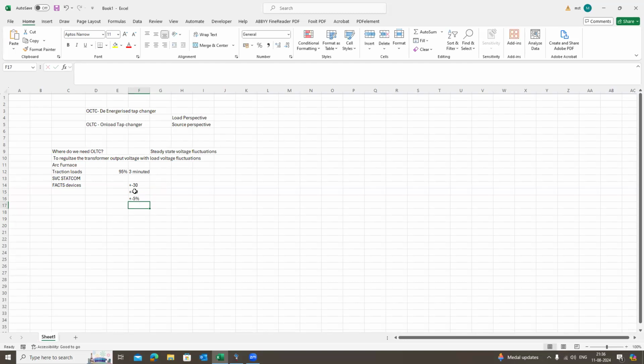Okay. So also we need to know what the response time is, whether it is in milliseconds or microseconds, or a few seconds, or the OLTC will operate in a few minutes, etc. So OLTC range probably comes with a time delay. If you have scenarios like sudden fluctuations in the voltage due to maybe some cloud event in a solar plant, or applications of the arc furnace, sudden traction pickup loads, etc., there this OLTC will not be able to help. Okay. I hope this is clear.